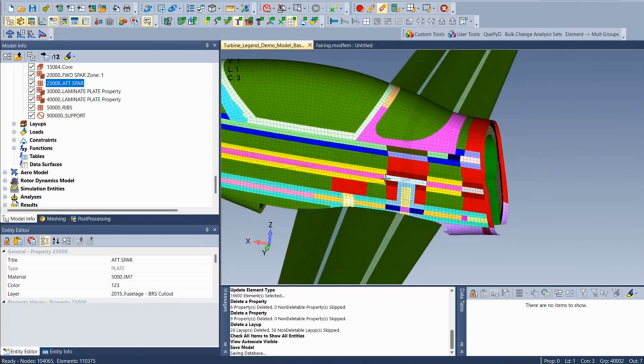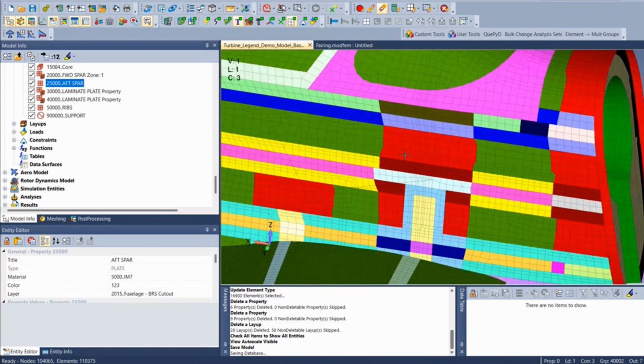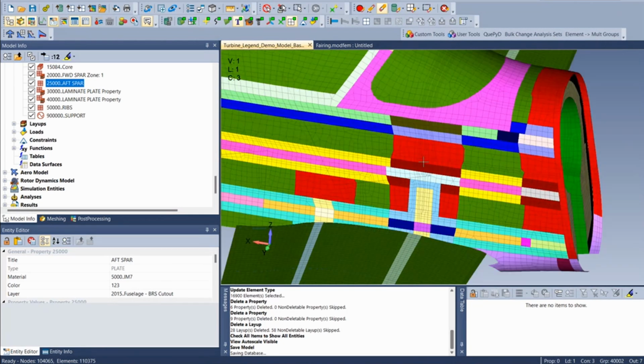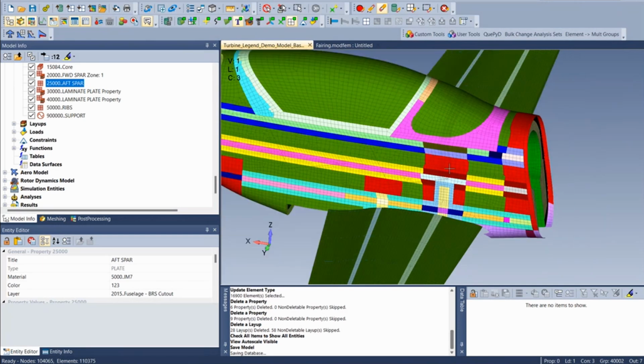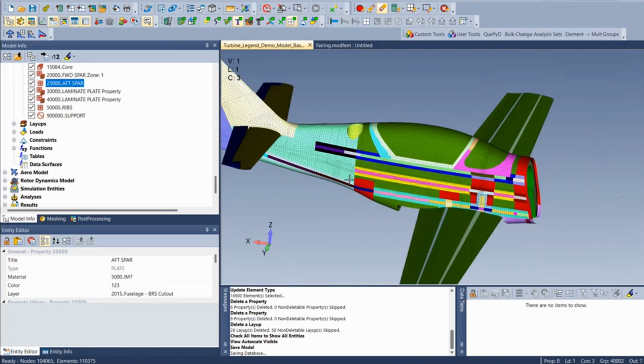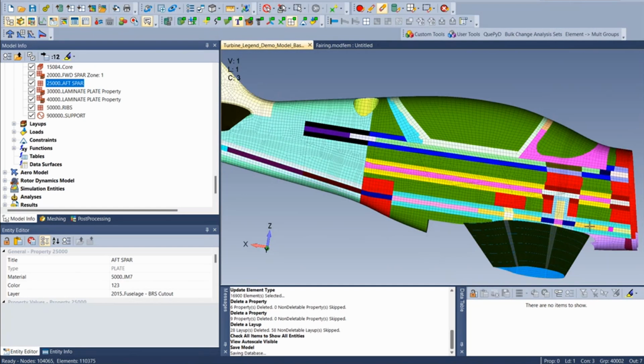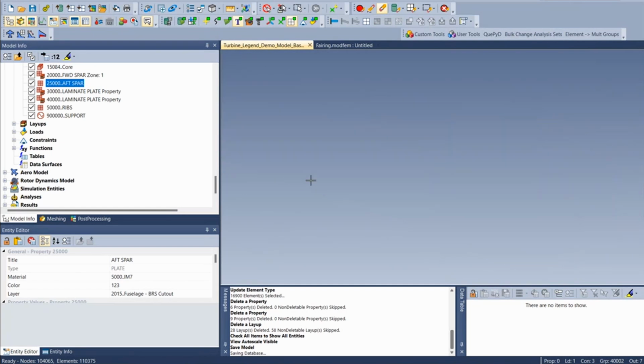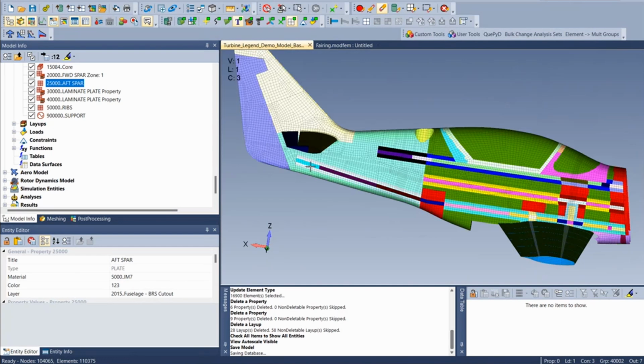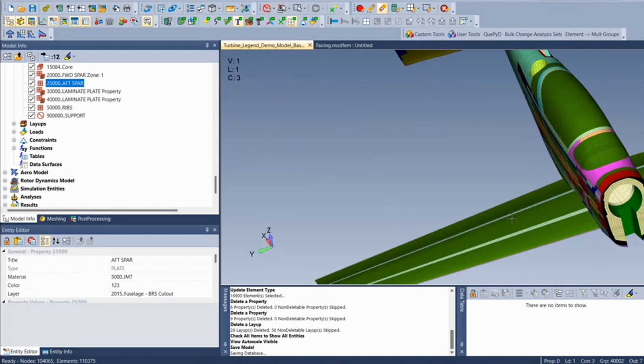In the past, for each one of these zones, you had to define and orient an individual PCOMP property. And it became a real nightmare when you wanted to say, hey, I want to add a ply here, or I need to drive this ply across a bunch of different zones because, for instance, I had to add uni that went all the way back here, and this required quite a few different PCOMP zones. And then if you changed one property, you would have to change all of them across the entire structure, which obviously is a very time-consuming process.